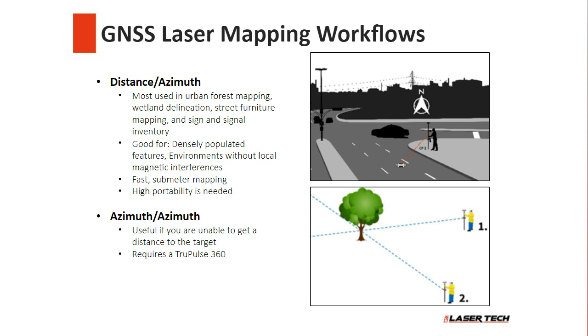He measures distance and azimuth. And from his known location, if he's got declination applied properly to the compass bearing, that'll generate a good georeferenced coordinate for that remote target. So, super quick method here. You can imagine if he had 10 or 15 objects to shoot around there, he could just pop them off really quick and put all those points into the data set.